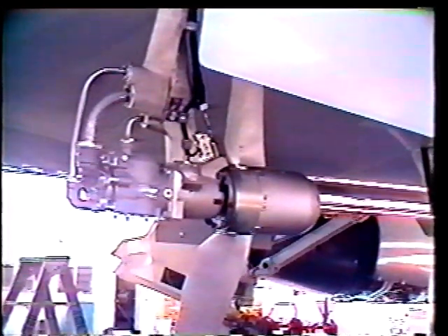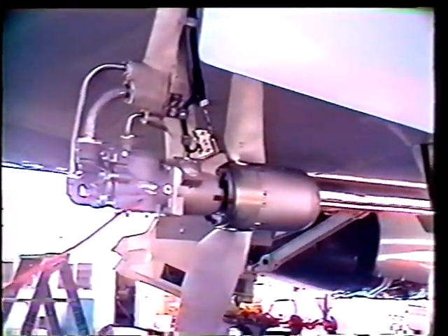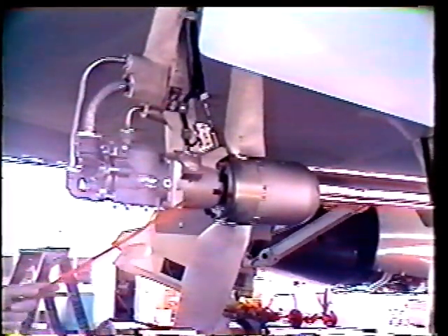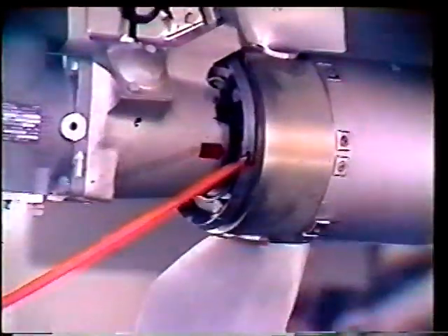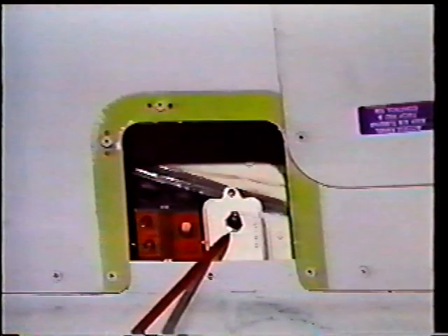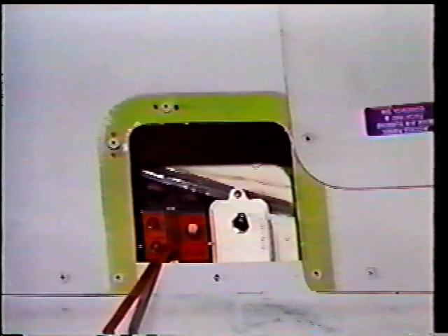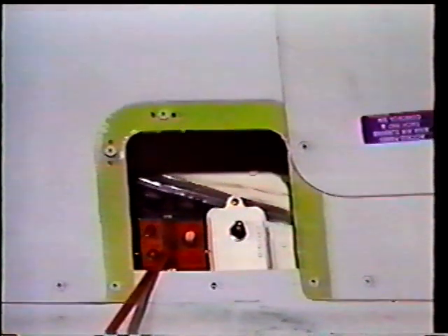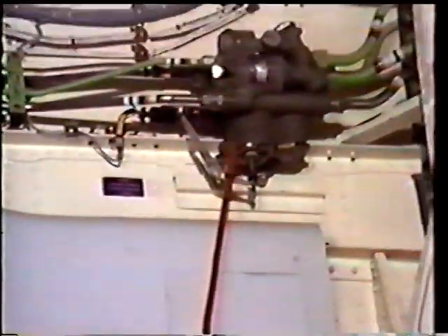To retract the RAT, the turbine must be properly centered on the strut. This is accomplished by carefully aligning indicator marks on the propeller hub and swing arm. In addition to deploying the RAT, the ground manual switch will also retract it. Located next to the ground manual switch is a tachometer module. Located above and inboard is the RAT checkout module.